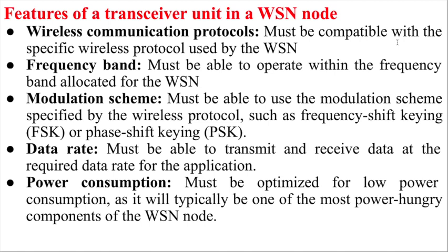So that means the given protocol is specific. Say for example, your other nodes support Bluetooth, then definitely you need to use the unit which is Bluetooth enabled. Otherwise, how can you communicate this information to the other nodes? So communication protocol is fixed with respect to the unit. So when you work on the unit, you need to check that this unit supports whatever communication protocols your other nodes already use.